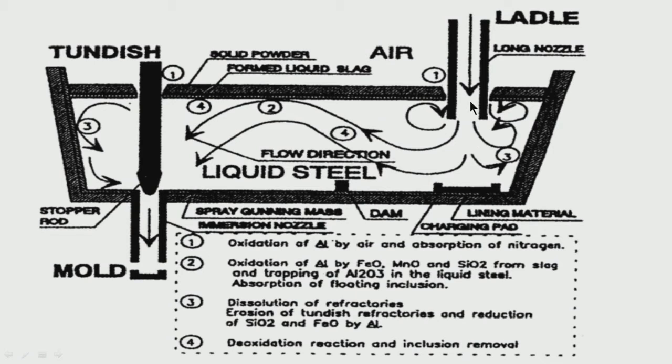We do not want liquid steel to go straight away to the exit of the tundish. Why? We want liquid steel to remain for some time in the tundish. What we call the residence time. The residence time of liquid steel in the tundish should be high, so that whatever inclusions or exogenous entrapments try to ingress in liquid steel will get adequate time to float up.